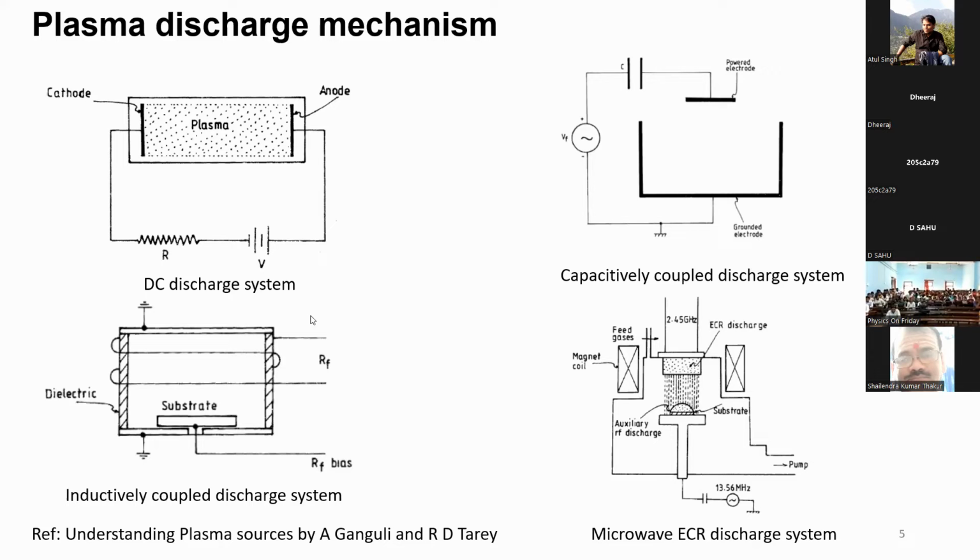Okay. The other part is, instead of a static DC bias, you can use an AC voltage. This one is a pure AC voltage; any DC is blocked here, and it is applied between two electrodes. So it is called capacitive. This plasma also forms like a capacitance, and we call this a capacitively coupled discharge system.